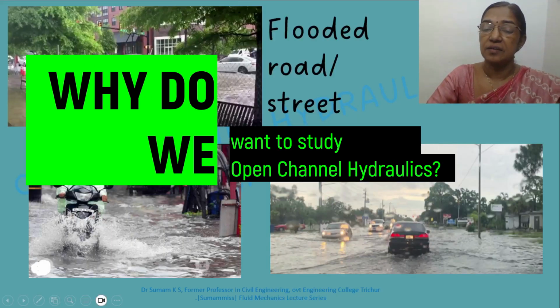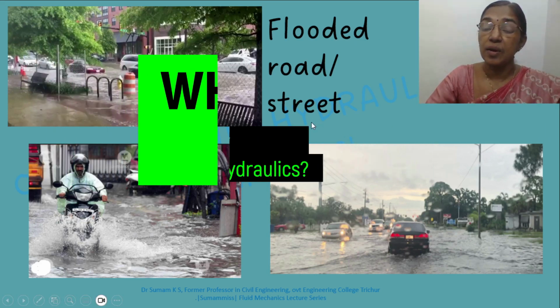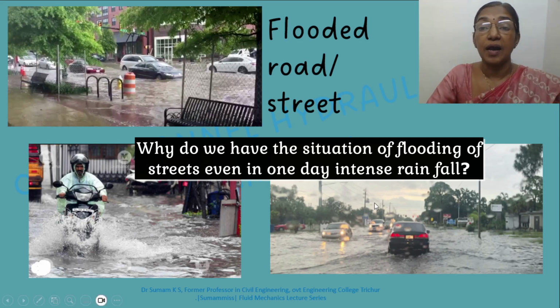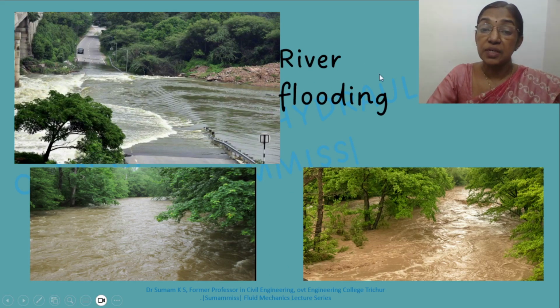Look at this figure. The figure represents the flooded road and street. Why do we have the situation of flooding of streets even in a one-day intense rainfall? So it may be due to the improper design and management of open channels and drains. Many a times the villain will be the inadequate slope and inadequate cross-section of drains. Most of the times the slope provided to match the ground slope shall be excess in certain places and inadequate in some other places.